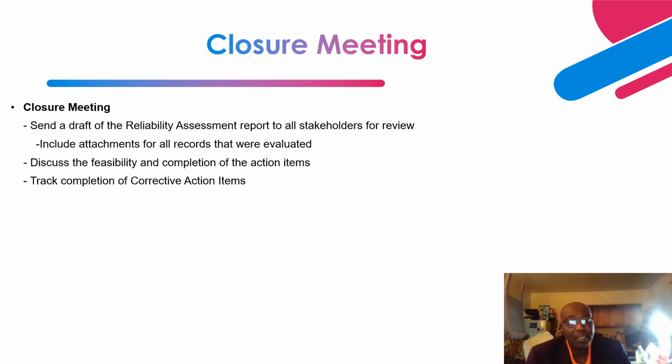Next is the tan delta, the power factor of the insulation system, both the thermally upgraded paper and oil. If the power factor is greater than 1%, then that tells you there's a problem inside, with contamination and moisture intrusion. Because for a newer transformer, I'm expecting a power factor of about 0.5%, and for a service-aged transformer about 0.5% to 1%. So these are typical examples of how you evaluate your criteria.